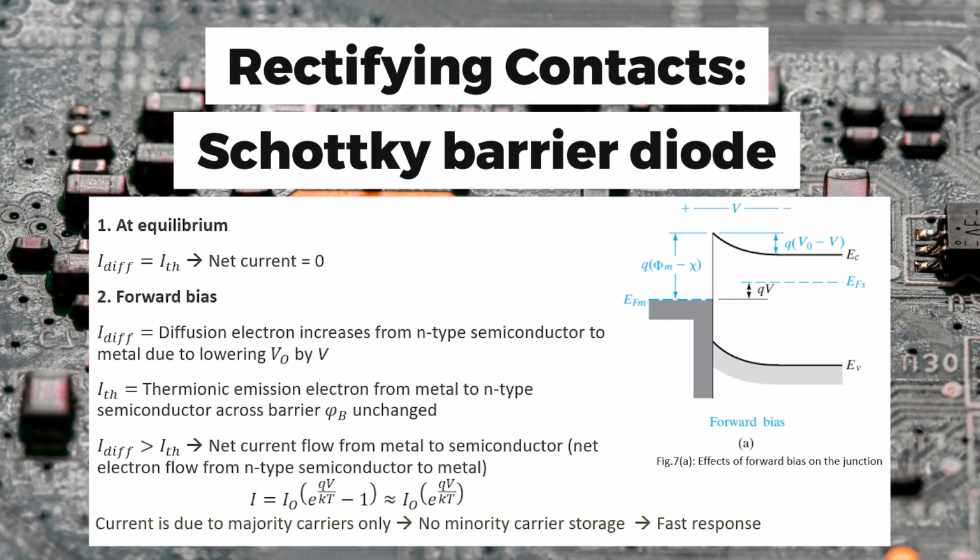As a result, electrons in the semiconductor conduction band can diffuse across the depletion region to the metal. This gives rise to a forward current from the metal to the semiconductor through the junction. Conversely, a reverse bias increases the barrier to V0 plus Vr, and the electron flow from the semiconductor to the metal becomes negligible. In either case, the flow of electrons from the metal to the semiconductor is retarded by the barrier phi m minus electron affinity. Electron affinity is represented as psi.